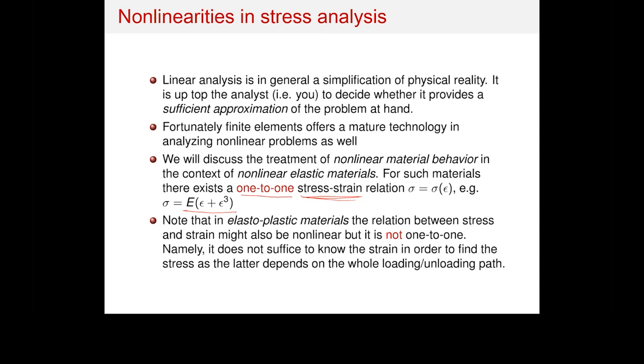Okay, I just mentioned that as well, since I'm discussing nonlinear material properties. For example, if you have a fire, the material properties would change, and it is going to be a nonlinear behavior, the type of failure you have eventually in there. The temperature would keep increasing due to the fire, and this would lead into a change in the material properties as the fire is getting hotter and hotter, or the building is heating up.